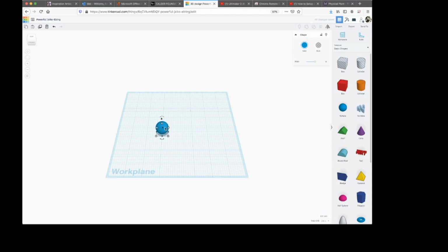So now if I select my sphere, when you roll your cursor over one of the handles, so the handles are these little squares that are on the edge of the form, it'll give you your dimensions, right? So in this case, this is just over 1/4 of an inch. Let's say that I want to make this, that's going to be maybe a little bigger than I want it to be. So let's maybe make it a 1/2 inch. So I'm going to change these to 0.5.